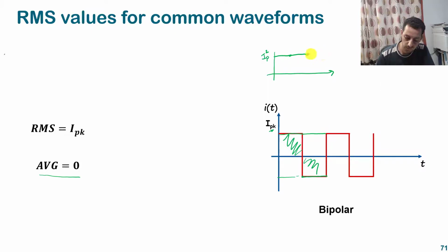And continue. Okay, so the square of this signal is a DC signal, and when we go to the RMS value, it will also be the same as I peak. But here the average value is different because we now have a different distribution of the positive and negative values. I think this is very simple now, but we have here I peak and the same I peak value here.